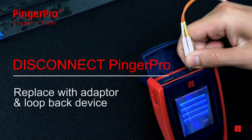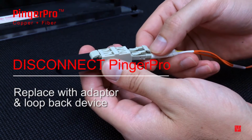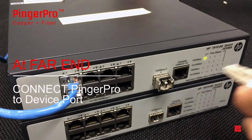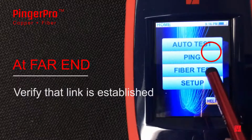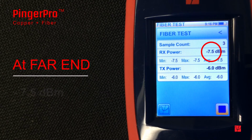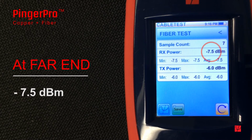Disconnect the PingerPro from the fiber and replace it with an adapter and a loopback device. Go to the far end link connection port and connect the PingerPro to the device port. Verify that a link is established and measure the optical power, which should be close to the same level as the other end. In this example, the measured level is -7.5 dBm, which is close to the level at the other end.